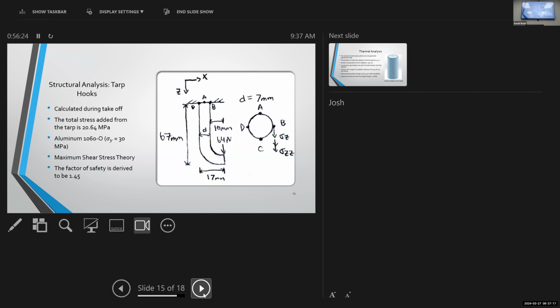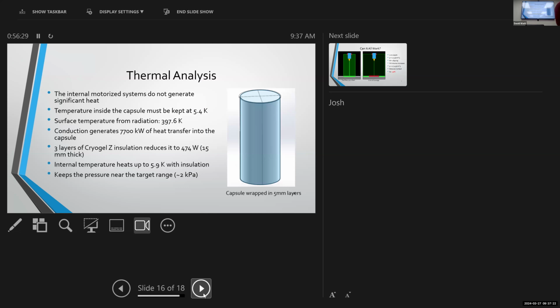Okay. And for the thermal control analysis, because you do have motors and the power supply, have you considered that those may also generate heat in addition to radiation? I'll tell you what, we did consider it. What we determined was that the time the motor would spin on the wheel lock was almost negligible, because it was only a 10-degree rotation. Oh, okay. Compared to the sun radiation, if it's really, really small, maybe show some number to me.